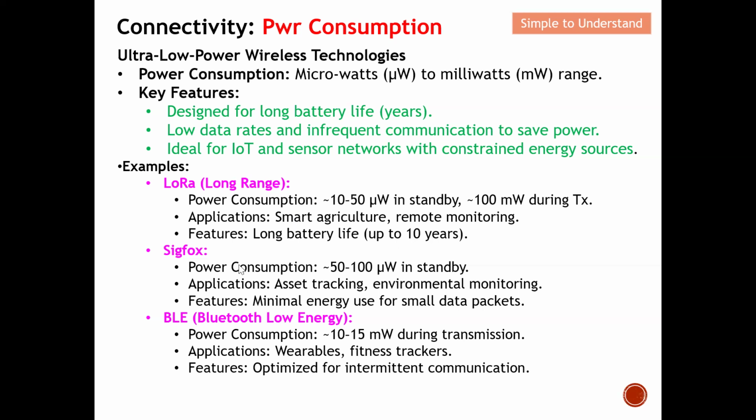For Sigfox, the power consumption is slightly more than LoRa, but in most cases Sigfox doesn't consume a lot of power. Most of the time, the Sigfox end device is under deep sleep. So basically they are mostly in deep sleep. For Sigfox, probably up to 100 microwatt in standby.